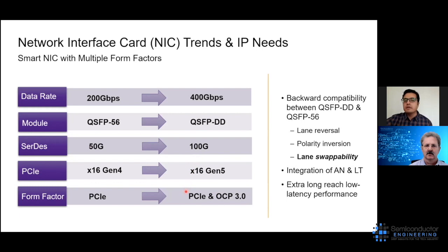And finally, there are different form factors which are being deployed today with the NIC. So PCIe and CEM form factor was dominant in the previous generation, but Open Compute Platform has come up with the OCP 3.0 form factor, which has started seeing traction here. So a lot of new designs are trying to address this OCP 3.0 form factor. And these changes require some new features from 112 gig SerDes. Let me talk with you about some of those which are specific to this NIC application.